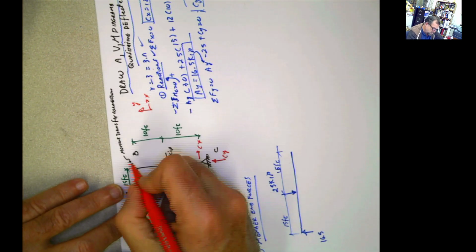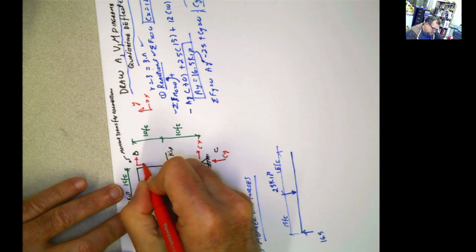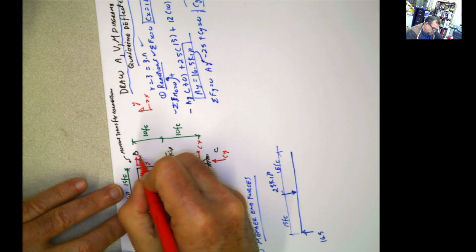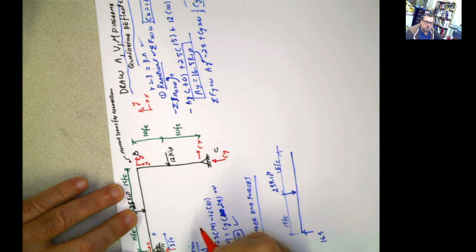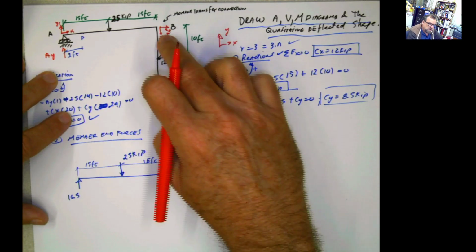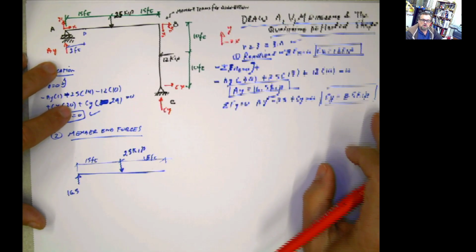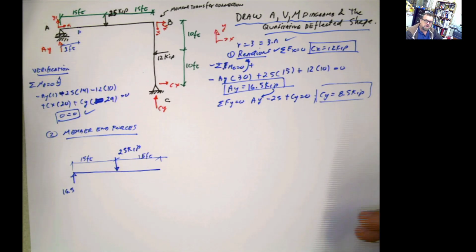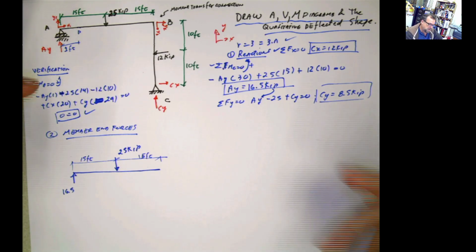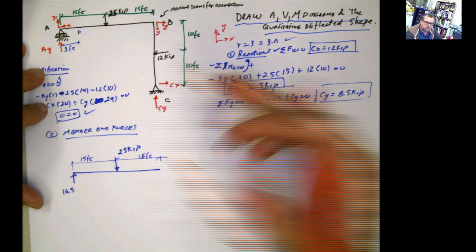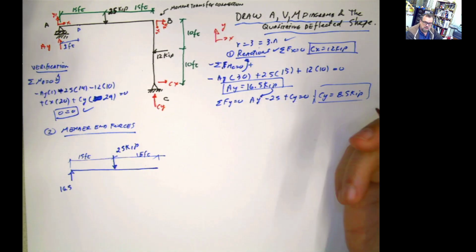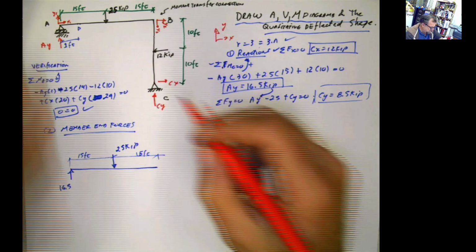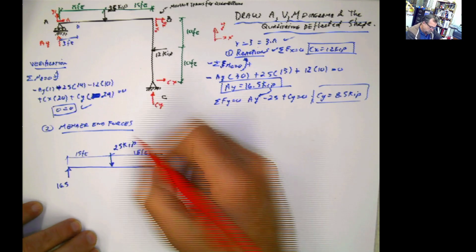And I'm going to say, oh, look at that. This is X2 and Y2, and that's going to be my local coordinate system, which is rotated with respect to the global coordinate system. The reason for that is because when you're drawing shear and moment and even axial, you're going to need that. Depending on that coordinate system, your diagrams are going to be plotted. So this is very important, even though I'm not doing it right now for everything else.